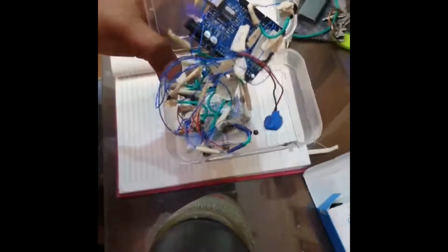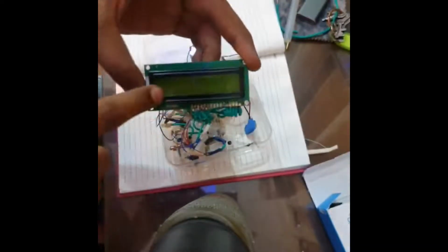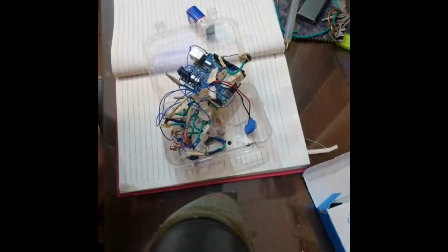There are resistors connected to each and every LED, as well as the photodiodes to control. There's a piezo buzzer which gives out a small ping as soon as you give an input or there is movement in the round numbers or the game restarts. And this is the soldering that went into this. This is faulty because it only displays one line over here. I can turn it on, but only one line works.